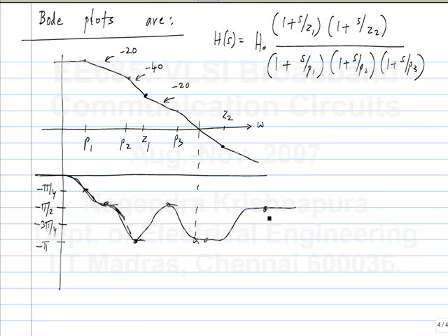Okay. So, what can you say about the number of poles and zeros before the unity gain crossing? Can I have any number, but is there a relationship? Pole minus 0 should be 1, right? Because if you have 2 poles, I mean the total, let's say the poles are well separated before, so each pole gives you a phase lag of pi by 2, each 0 gives you a phase lead of pi by 2.